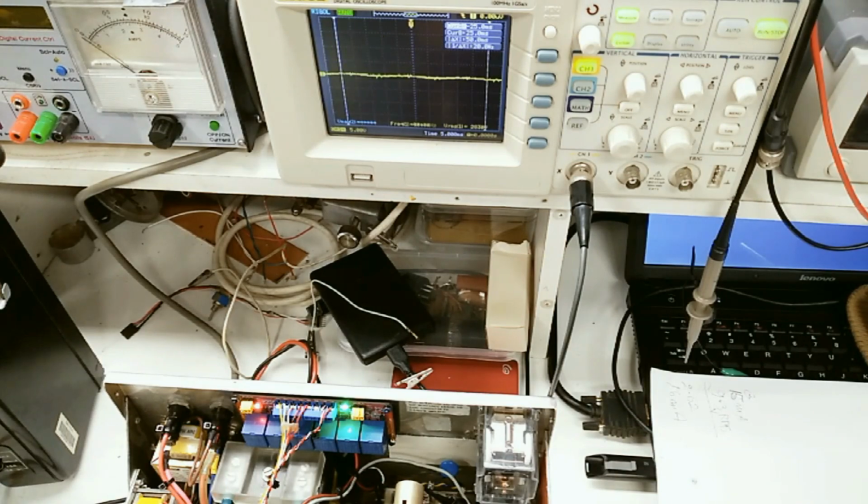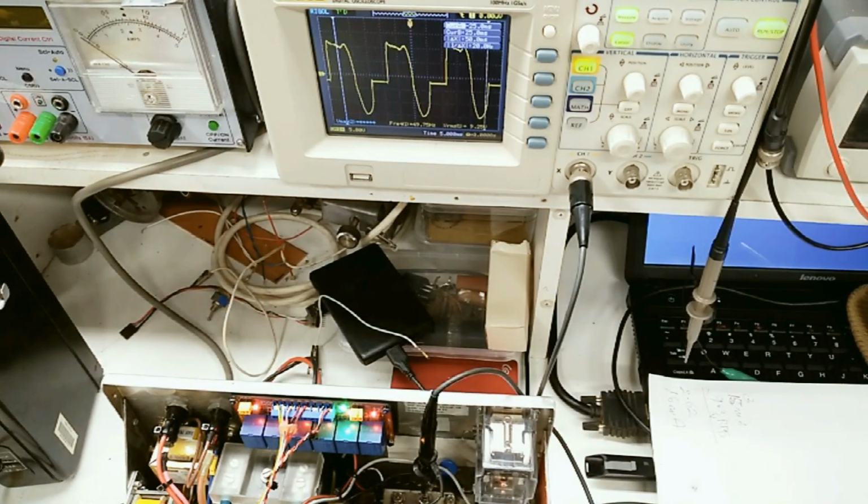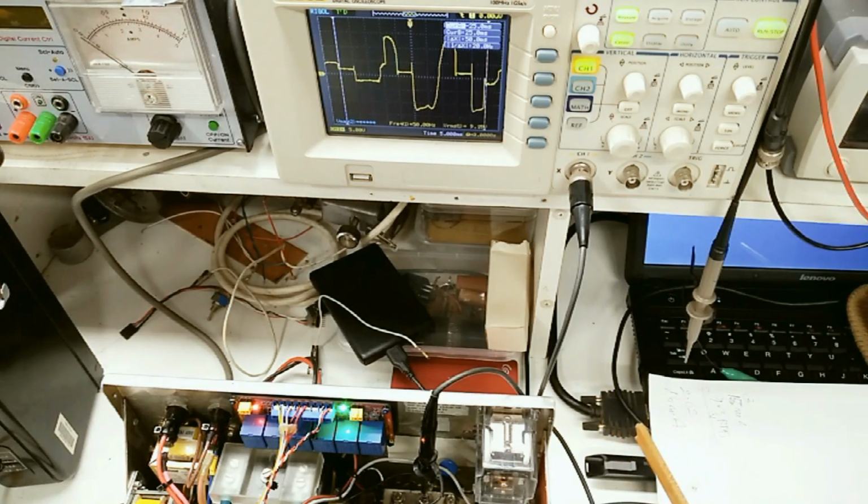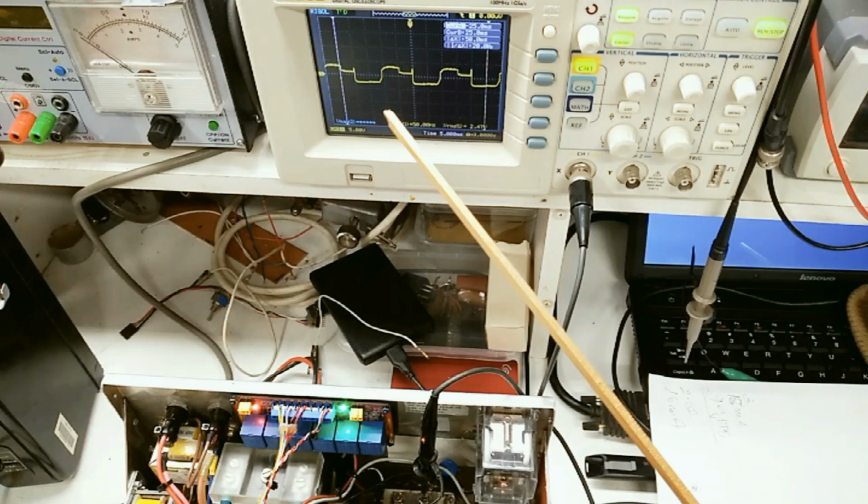So the higher the load, okay, hang on a minute. Sorry, the probe clip jumped off, so that's what I'm getting. Now I will show you when I bypass the resistor. So now I'm going to bypass the 360 ohm resistor, and I get that. So it's a big improvement.